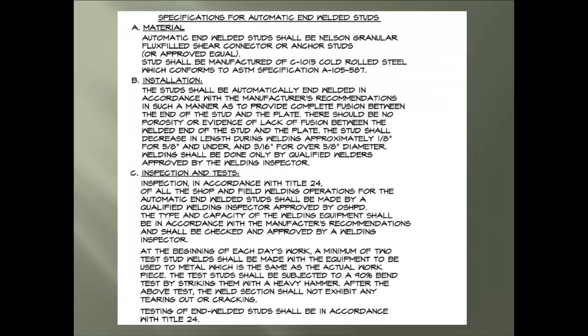Next, we come across the information on automatic and welded studs. Here are some items of interest. Here is the manufacturer name of headed studs found throughout the industry, the Nelson stud. We see the qualifying of welders will be by the welding inspector. Here is the way the California Building Code is addressed at times, Title 24. We see OSHPD is the jurisdiction having authority for this project.